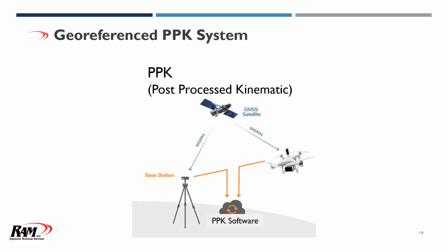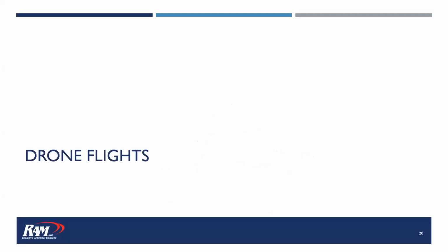But the thing we found is more often than not, the base rover setup does probably the vast majority out there, but occasionally these situations do exist where the PPK is very helpful to accomplish the mission, even though we've got some inaccessible areas and things like that. Both of these will give us a very high degree of accuracy on our surveys.